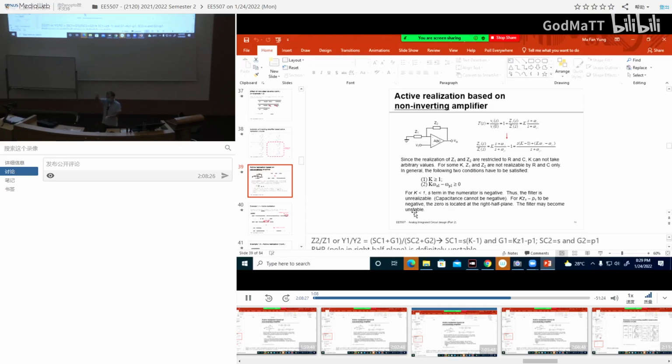your step response may have a lot of ringing. I put a step in the input, I look at the output, it's ringing, oscillating, and after a long time, then it's stabilized. Which is not good for some applications. So if my phase margin is 90 degrees, you find that it's quite clean. I put a step input, it will rise exponentially to the output, so there's no ringing.